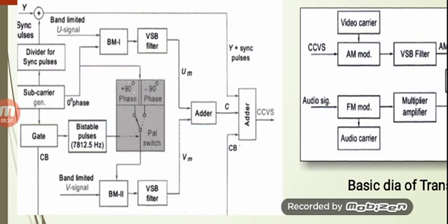Now here what we are going to do is, the other signal which we are going to modulate will be modulated for plus 90 degree or minus 90 degree. Now when we modulate them for plus and minus 90 degree, obviously the basic requirement for quadrature modulation is that there has to be a difference of 90 degree, so that the 90 degree difference is maintained and the signals will not get mixed with each other, and then plus 90 degree and minus 90 degree will be taken forward.